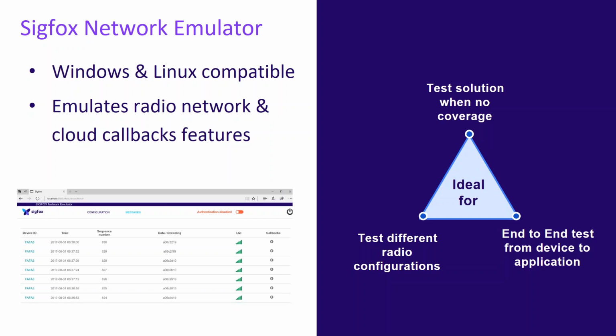The other use case is, as you may know, with Sigfox, we have different frequency bands. So we've got a radio configuration 1 in Europe, which is using 868 megahertz. But if you go, for instance, to the United States or Mexico, it's a different frequency, which is 902 megahertz. If you go to Latin America or to Asia, it's going to be 920 megahertz. So you've got different radio configurations. And using the SDR dongle, what is interesting is that you can choose from the different radio configurations and test your IoT solution for different regions.